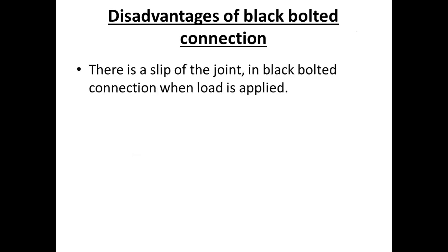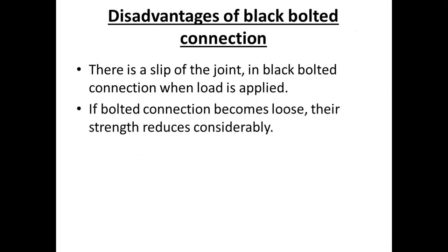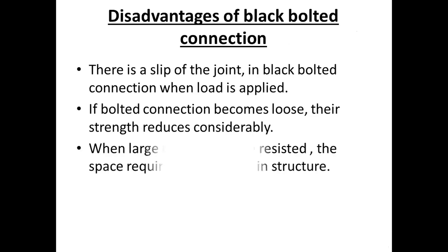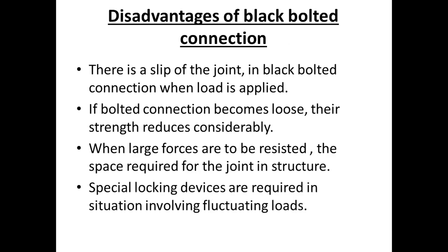Now we see the disadvantages of black bolted connection. So there is a slip of the joint in black bolted connection when load is applied. If the bolted connection becomes loose, their strength reduces considerably. When large forces are to be resisted, the space required for the joint is large, and special locking devices are required in situations involving fluctuating loads.